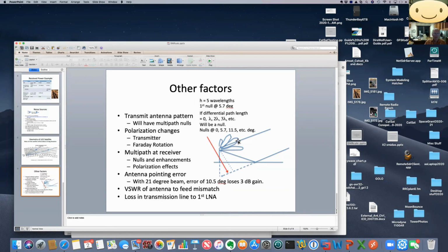Well, one simple way of doing this: every time the ground receives a valid packet, which it can check and be fairly certain is valid by doing a cyclic redundancy check or some type of error control check on the data, the ground then acknowledges and tells you what packet number it got. And if the ground didn't receive a packet, it does not send an acknowledgement. And in that case, the satellite says, wait a minute, where's my acknowledgement?